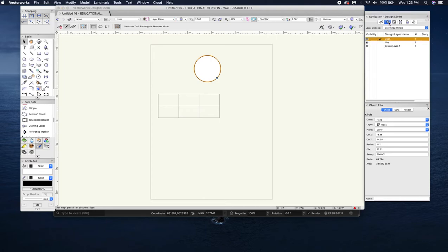Right, so going back to the layers. There are different ways that you can see your layers. The default is gray and snap others, which means all of my other layers that are not active are going to be grayed out, but you're going to be able to snap to the different objects on different layers.